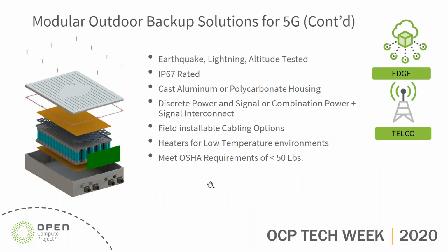So I want to show you a little bit of an idea of what the inside might look like. In some ways, it's kind of like Lego. I have an array of cells in there, and what you'll see is a larger gap between them than in packs of old, where you used to just stack your cells right next to each other and glue them together. But now we're looking at gaps of typically 5 to 6 millimeters in between. So we have to have cell holders to keep them all in place. And because each one of these cells is roughly 70 grams, we also have a decent amount of mass to contend with, plus we have to do the termination of each one of these cells. So we're looking at anywhere from 80 to 160 cells that we have to terminate and put in the pack. And the yellow plates there are the heaters that we'll put in.